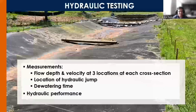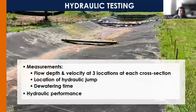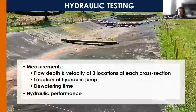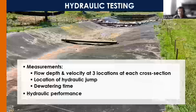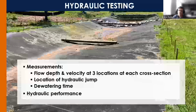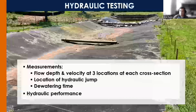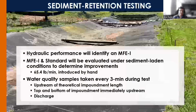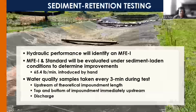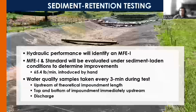We primarily were looking at hydraulic testing with some sediment-laden testing after. Measurements we were taking are flow depth and velocity at 3 locations at each cross section, to generate a flow profile, a location of the hydraulic jump, which indicates the length of impoundment, and where that flow begins to slow to non-erosive levels, as well as dewatering time to see if there are any recoverability issues. After hydraulic performance, we identified a most feasible and effective installation. Both that and the standard were evaluated under sediment-laden conditions to determine improvements in both sediment capture as well as water quality.